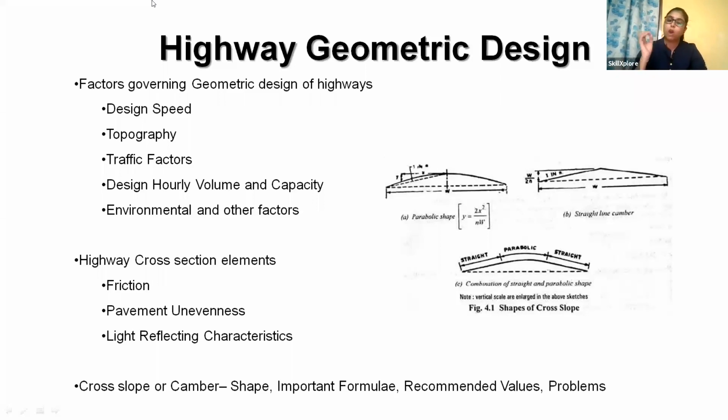In that Appian Way, what they did is they dug the pavement to some depth, maybe like 0.75 to 1.2 meter depth, and they filled it with big stones, and they leveled it. So there was no slope there. At that time itself, they understood that if there is no slope there, water will enter the lower layers, and that causes problems. And also it was uneconomical, because at those times, vehicles were not many. So this much thickness of pavement is not required.